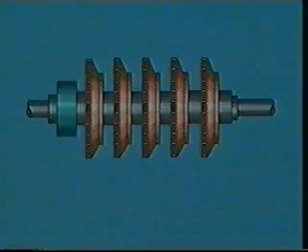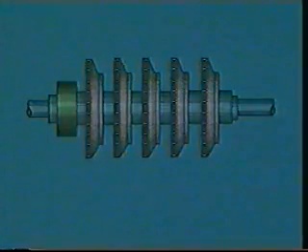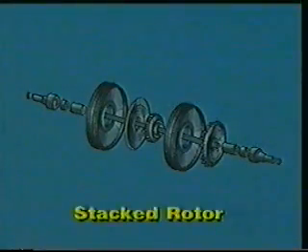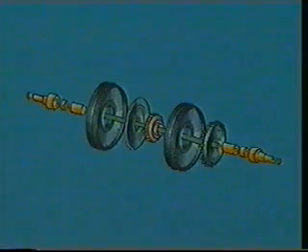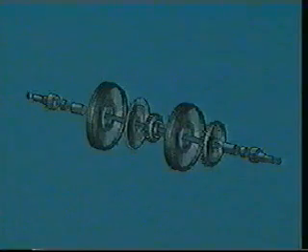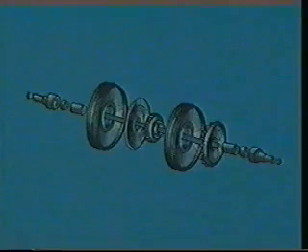In most centrifugal compressors, rotors are built with a balanced piston installed at the discharge end to relieve the thrust-bearing load. Stacked rotors consist of a stub shaft for each end, several impellers, a balancing piston, spool pieces, and other needed parts, all held together with a heavy center bolt. Although this type of rotor is always used in a stacked style vertically split casing, it can also be used in other types of casings as well.